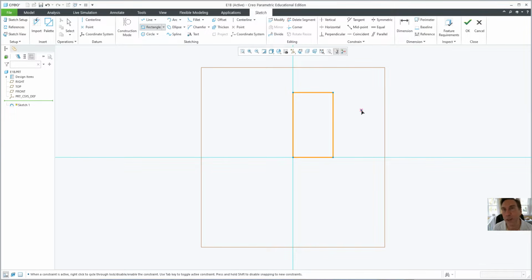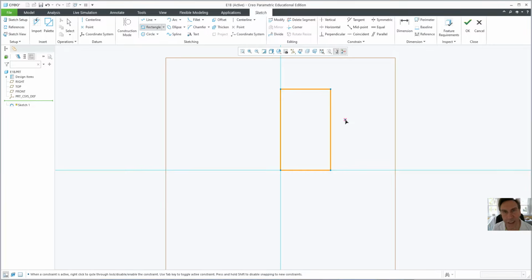Okay, now here's where we get to use the middle wheel. Scrolling the middle wheel will zoom in and out, and you could test that out if you want. But if you click on it like it's a button, it also enters into the next field. So middle click like it's a button on that wheel. And look at that, dimensions appear. And so now you can pull these dimensions down by clicking on them and holding them with the mouse button and just move it over to the right, move it over to the left. And let's say those are way too big, or this is going to be 3 by 5. To change them, it's super easy. Just double click. And now you could just type in 3 here.